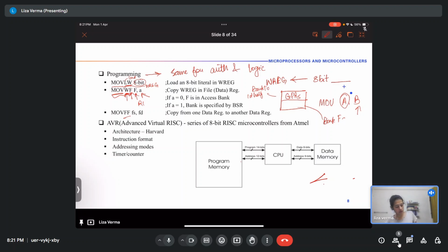Okay, I'll try writing with my hand then. So if you have 32 registers, you'll require 5 bits to number them, right? So the next five will be for your first operand, and the last five will be for your second operand.